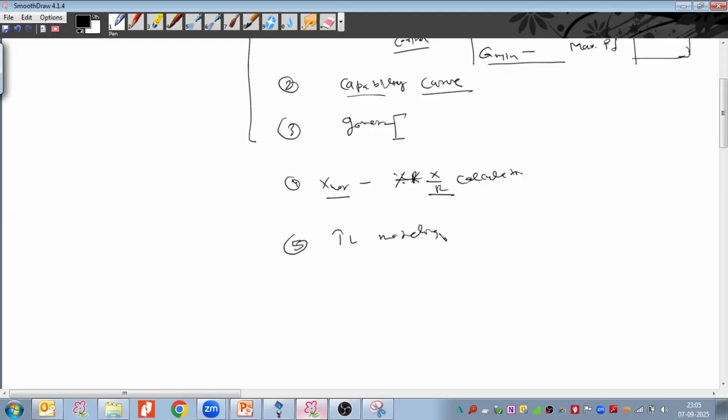In the transmission line modeling, we discussed that we have two options. First of all, we have to define the conductor length, and then when we go to the parameters selection, we have two options. We can take the default conductor library, select any specific conductor from that, and do the modeling. Or otherwise we can go to the parameters tab directly, click on user defined, and then we need to define the conductor resistance, reactance, and susceptance values.